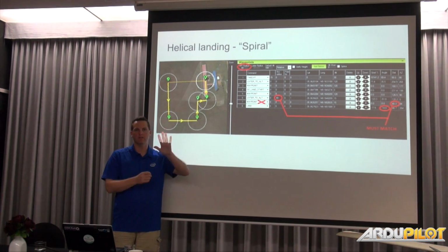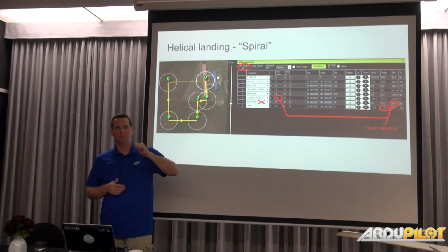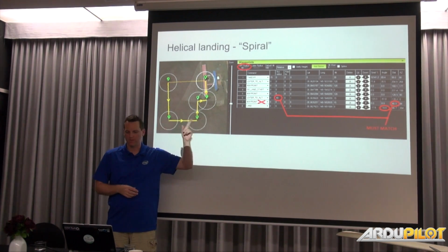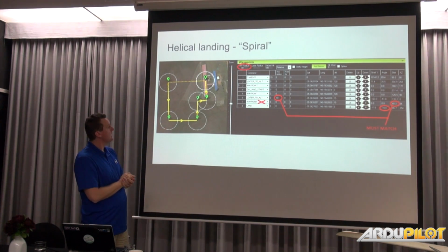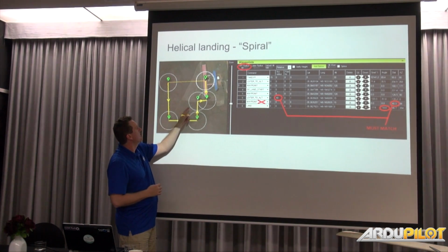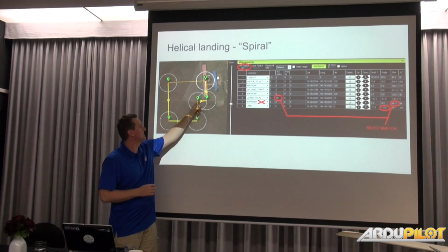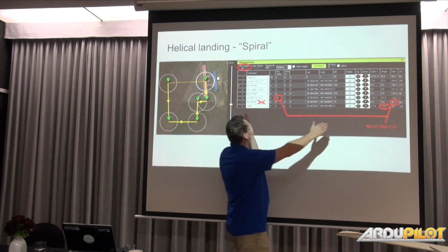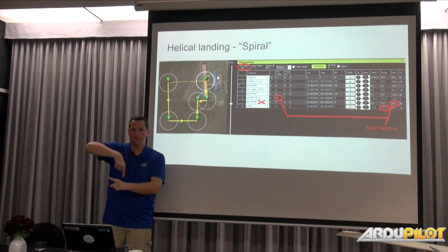I have 2 slides here. One that shows how I set it up, and then one that actually flies. So this is the setup for it. Point 2 is just you take off. I'm just loitering at some point, and then now 3 is the setup. And on 3 we are going around the turn. Point 6 and 7, we're going to be removing soon, but it gives us a good marker of distance when we're calculating. We can go over here and see the distance in meters between them. So you want to basically be loitering down over that point, so when you exit, you can achieve that.